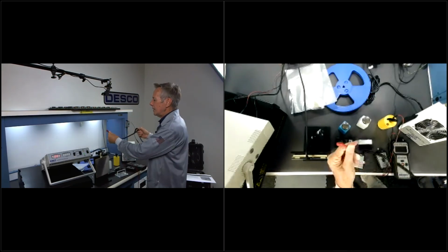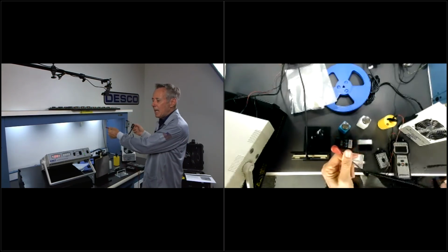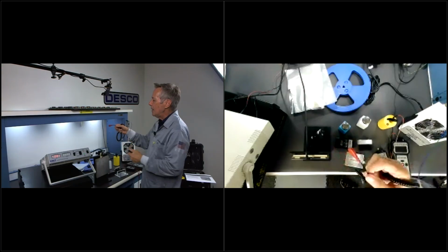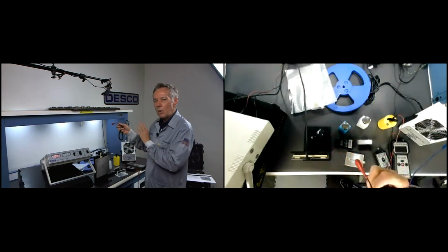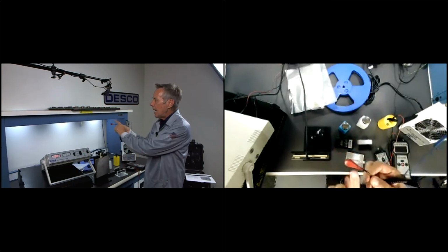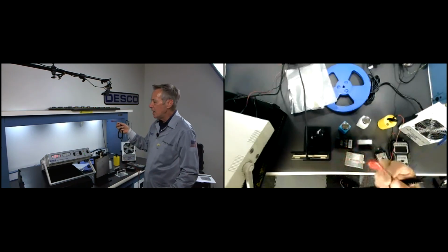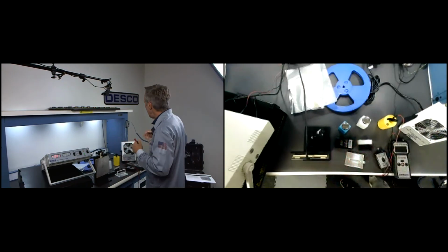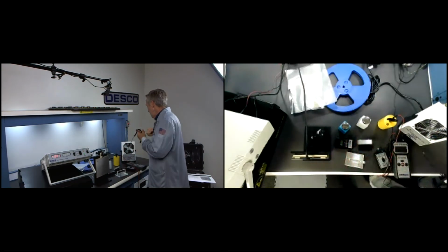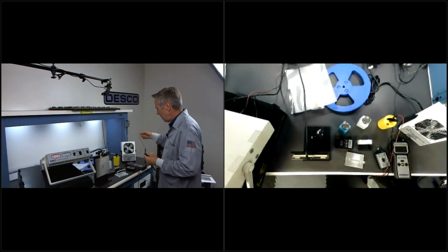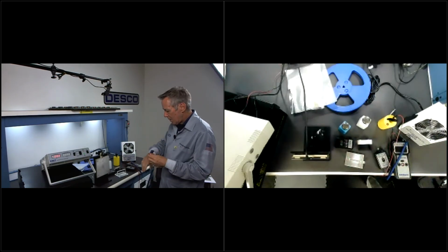Now I've got another cord here. This cord has a red molded head on it, and it's important to understand that the standard requires that if I don't have resistance in something, that I identify it with a red color. So that's what we've done here. This cord doesn't have a resistor in it. So I'm going to unplug this one. I'm going to put on my red-headed cord here.